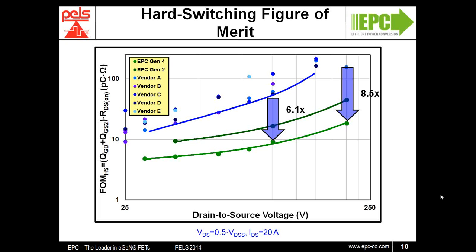So for these devices, how do they compare against similar high resistance MOSFETs? To do the comparison, we compared one of these generation 3 high resistance GaN FETs versus a second generation low resistance 100 volt GaN FET, as well as equivalent packaged MOSFETs with similar on-resistances. The only devices we could find effectively were the 30 volt BGA devices.